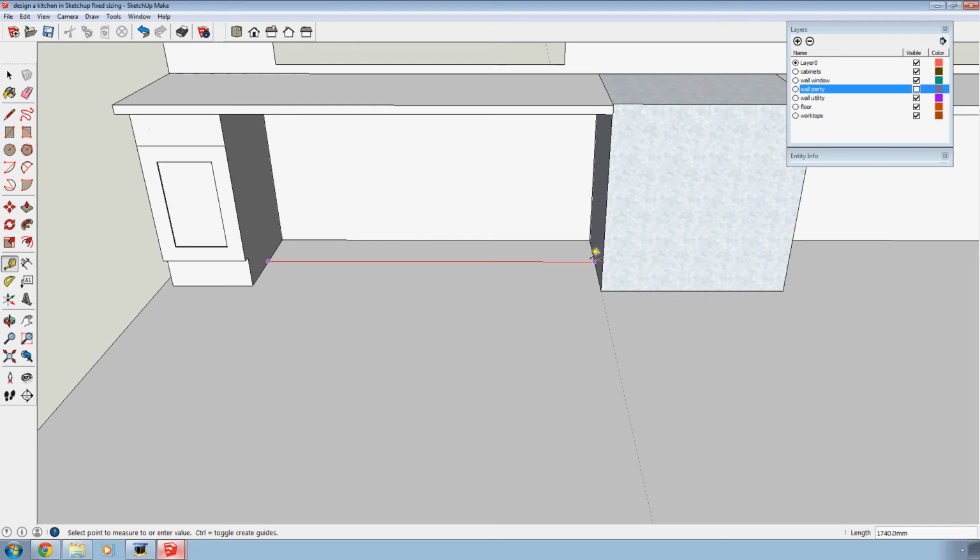Quite often things like wine racks might be that kind of width, and we might in fact have to use a 150 just to cope with this awkward measurement. So 1740, how can we divide that up? If we have 1740 and subtract 150 from it, then we'd be left with 1590. This is going to be easy actually. 1590, if we made that 1600, then that's obviously going to divide by 2 for 1800.